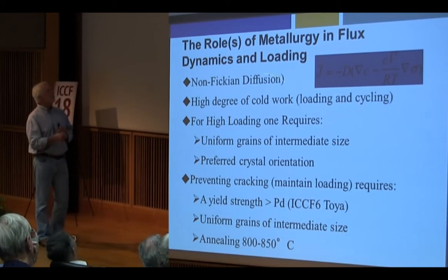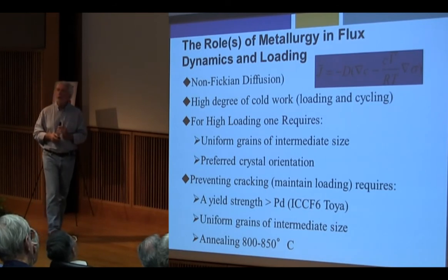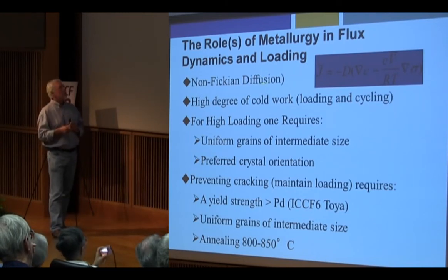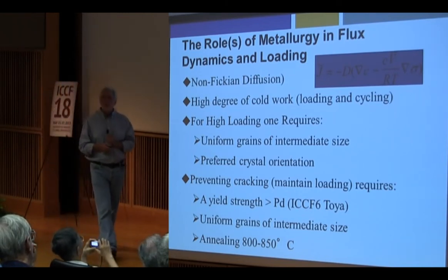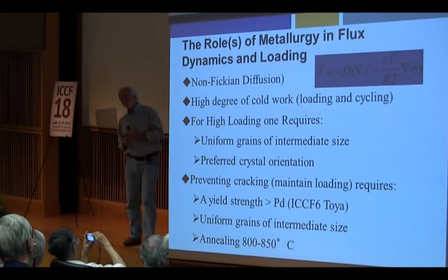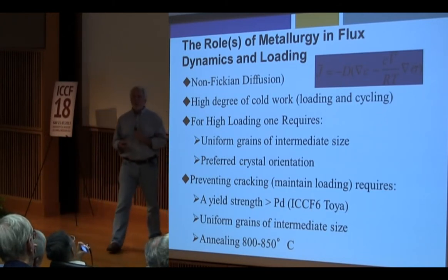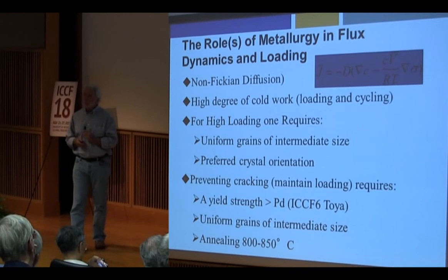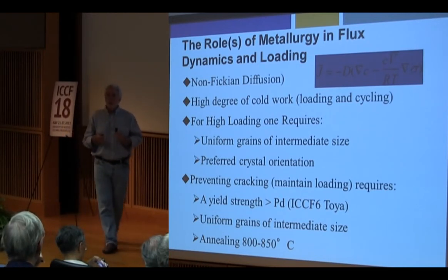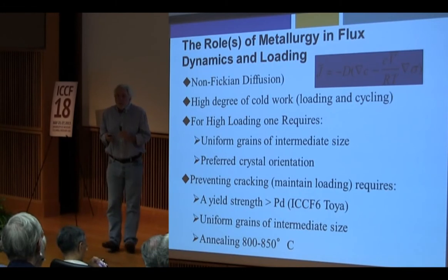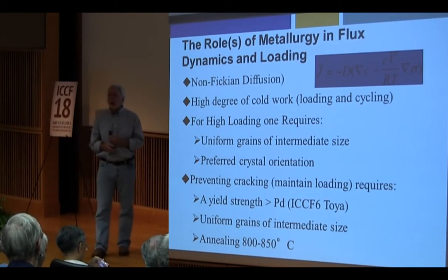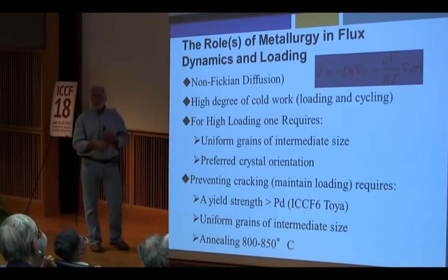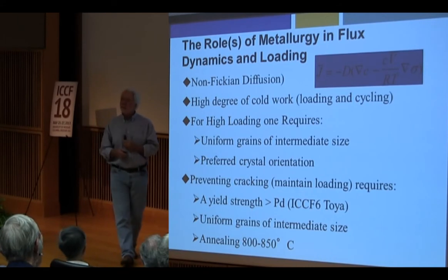Vittorio has covered a lot of this. What is the role of metallurgy in controlling this flux dynamic? Vittorio at previous times has done a beautiful job of explaining that the diffusion of the atom into the bulk material doesn't follow Fick's law. It doesn't follow Fick's law because the lattice expands. The expansion, if you like, thinking in simplistic terms, the system is being squeezed and pushed, and it says, I don't like this, and it pushes back. So you can develop a condition where, although you have a concentration gradient, you don't have any flux because the mechanical force is pushing back against you.